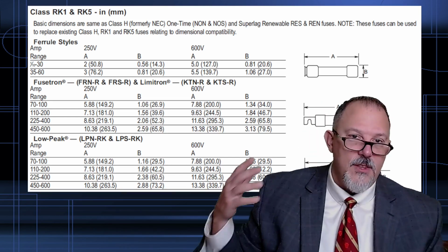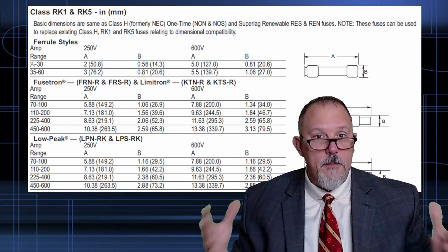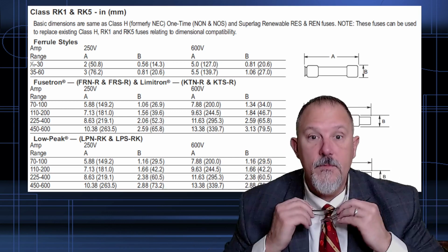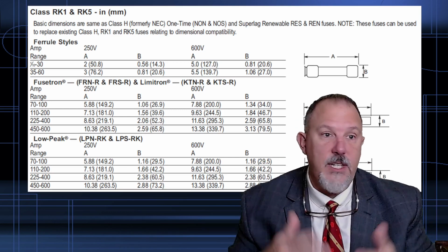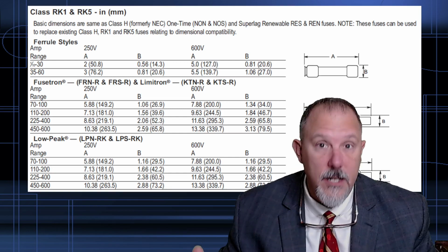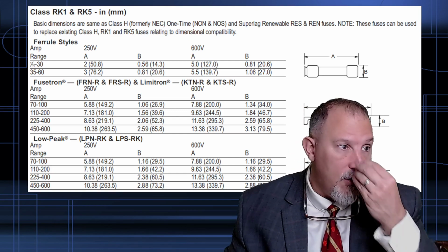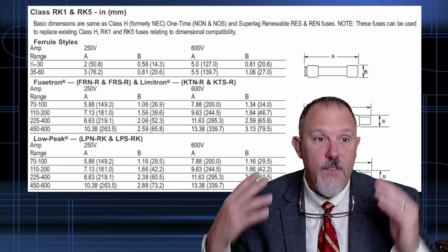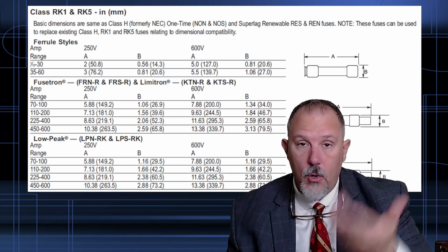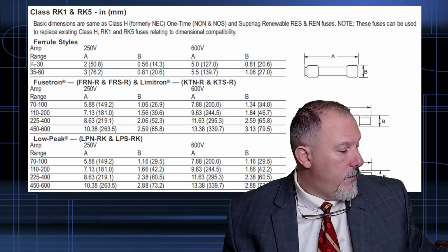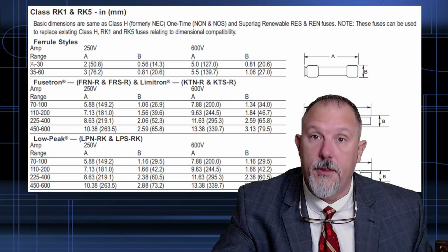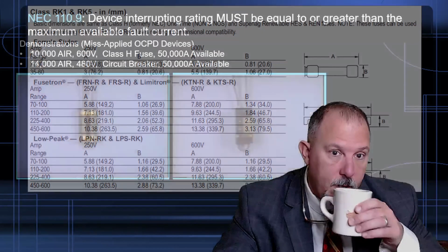But you'll notice the dimensions of the fuses. All manufacturers have to meet these dimensions, so that if I buy a Bussmann CC fuse, it'll have the same dimensions as a Mersen CC fuse, as a Littelfuse CC fuse. So all manufacturers of fuses will follow these standards to make sure that the holders can be used with each other's fuses.